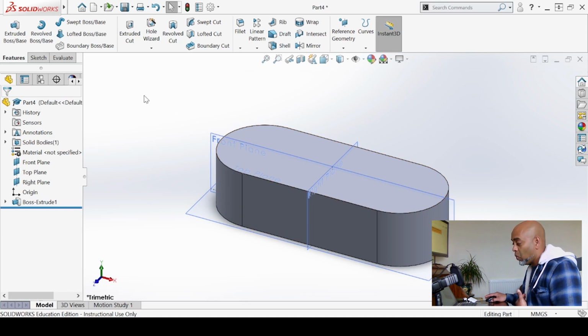Instinctively, I want to go into the Extrude Cut. I want to click on that plane, draw a circle, go into Extrude Cut and drill that hole out. However, that's not the right way, okay? From now onwards, if you are drilling holes for fitting fasteners through, or if you want to throw this into an assembly and this then goes on to something else, or there's another part that fits on top of this, it's a good idea to use something that's called Hole Wizard, okay?